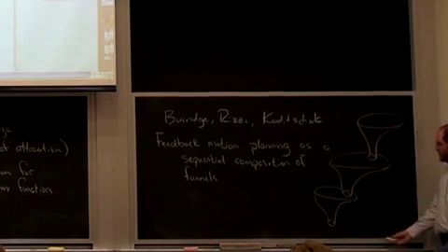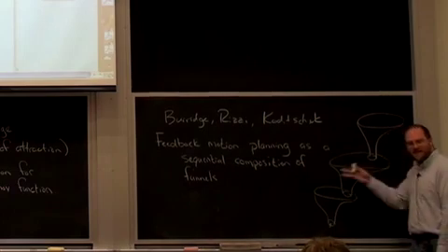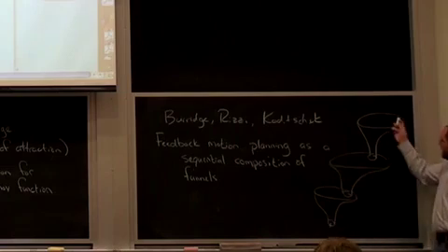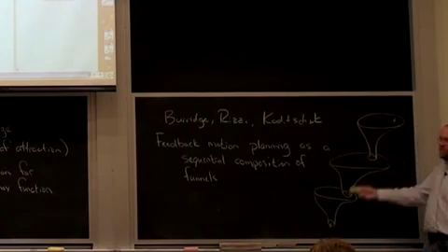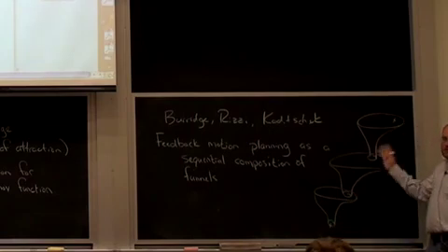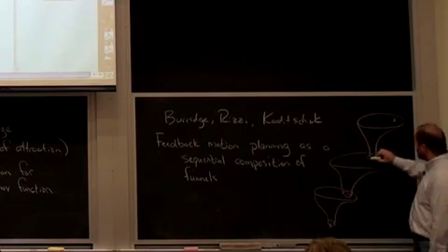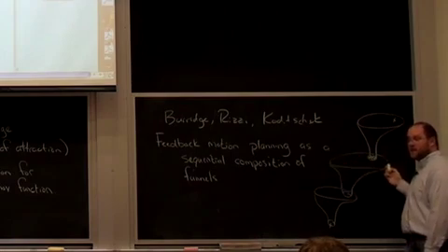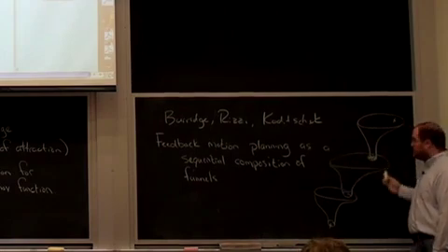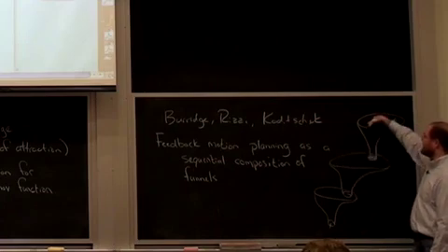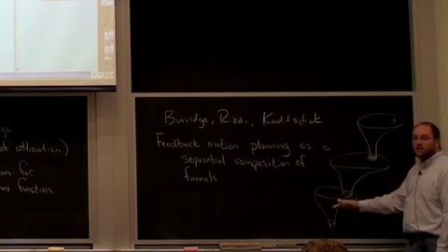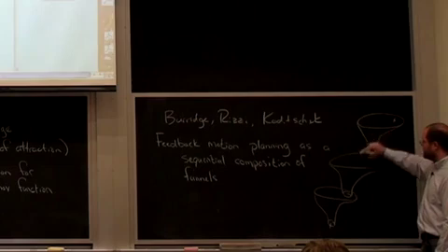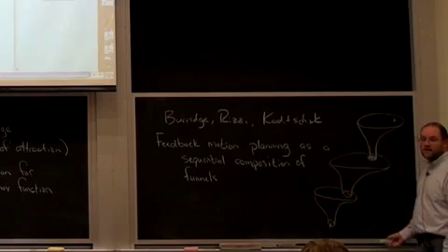So if my goal state is somewhere abstractly here in state space, that's not accessible from any one controller, I can't get from my initial condition to my goal with any one of my controllers, I can sequence these controllers, just making sure that the output of one funnel is completely covered by the input of the next funnel. Then that's enough to use these funnels as an abstraction to take away the continuous problem and give me a discrete planning problem, which just says I need to go through this funnel, through this funnel, through this funnel, and I can get to the goal.